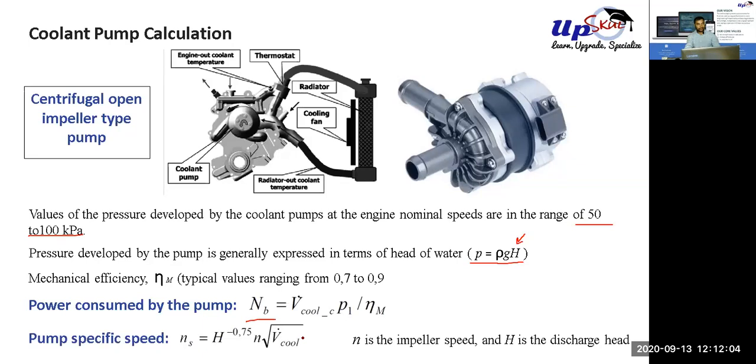Also, from the supplier catalog we can find more details. For example, the characteristic curve of the pump for any centrifugal pump. Okay, there is a characteristic curve, very important. For example, the flow characteristic, the pressure characteristic: how the flow increases or decreases with the change of rpm, how the pressure changes with the change of rpm. We will need this also to do the analysis, 1D or CFD, whatever you are doing, you need this data.